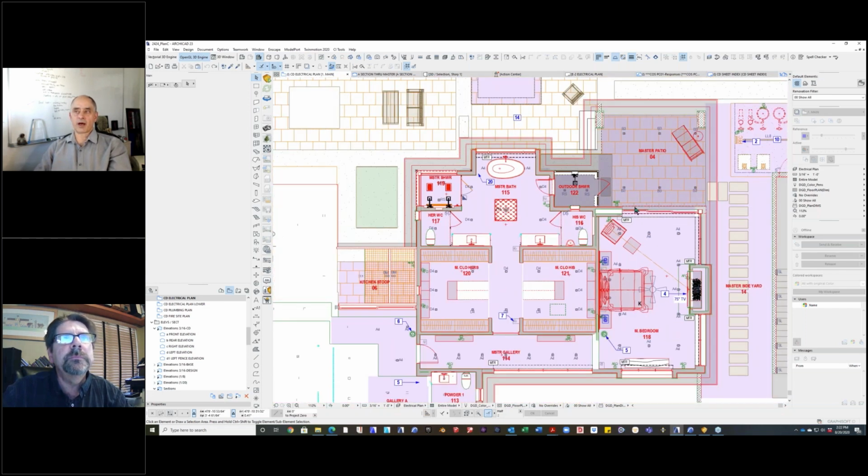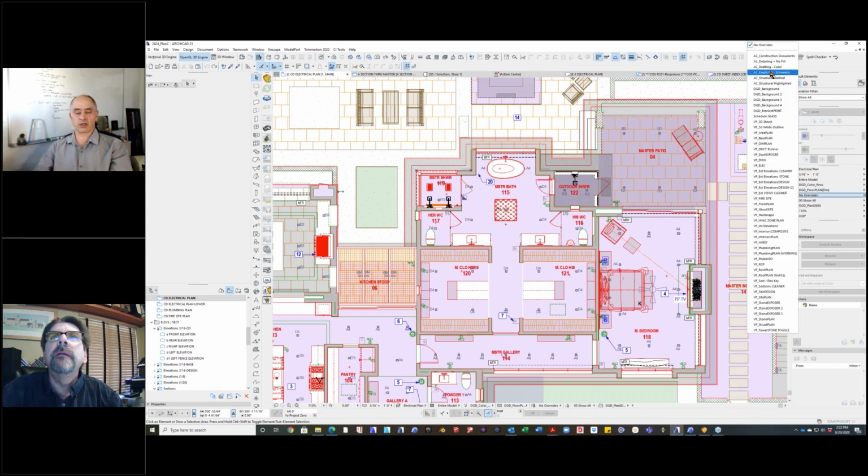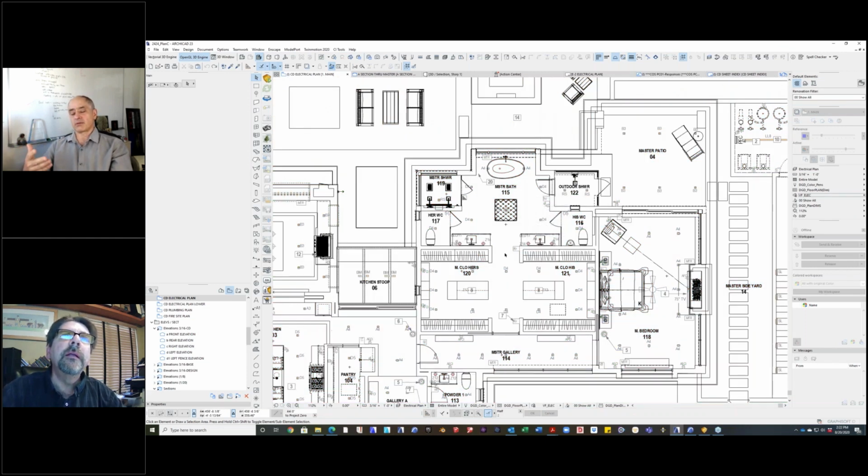So if you think about it, the pen sets are very specific because they're basically, this pen is this color, this pen is that color. And you might draw with a bunch of different pens, certain types of elements. There are different things in library parts. You use multiple pens, and in some cases you would literally have to do a lot of fine tuning of a lot of individual pens to get an effect. Here, we're doing a very quick criteria. If it's on a layer that starts with E, do something.